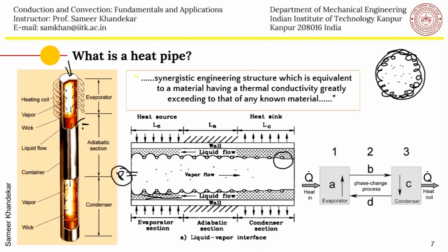That will be the pressure it will start showing, and of course the temperature will be the local temperature of the room where you have done the filling. Equilibrium will come, and all the liquid in the heat pipe will be in the capillary region. It will be here, and we will put only enough liquid so that it saturates this wick, and not more. So there is no extra liquid. All the liquid goes in the porous media, which is at the circumferential periphery of this cylinder, and the space in between is filled up with vapor.